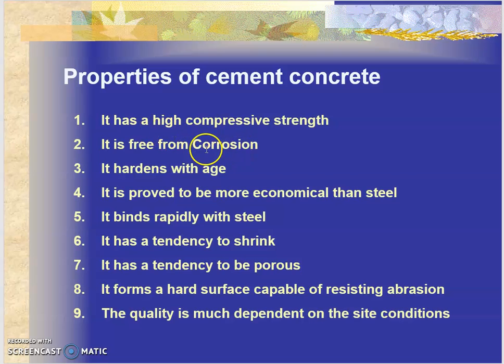There was a catwalk being constructed here only in Goa in MPT Harbour. Three catwalks were constructed in steel. They constructed one, corroded fender, second one again in steel, corroded fender. Now, why is it falling down? Because Vasco is a port, right? They were constructing it in water actually. It was not even offshore, in the water. So, when the ships used to anchor, for people to move from one dolphin to another, what is a dolphin? A dolphin is a group of piles.